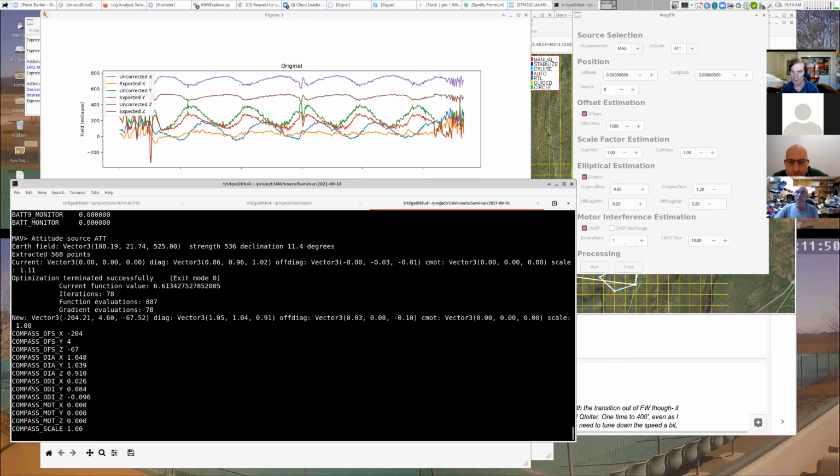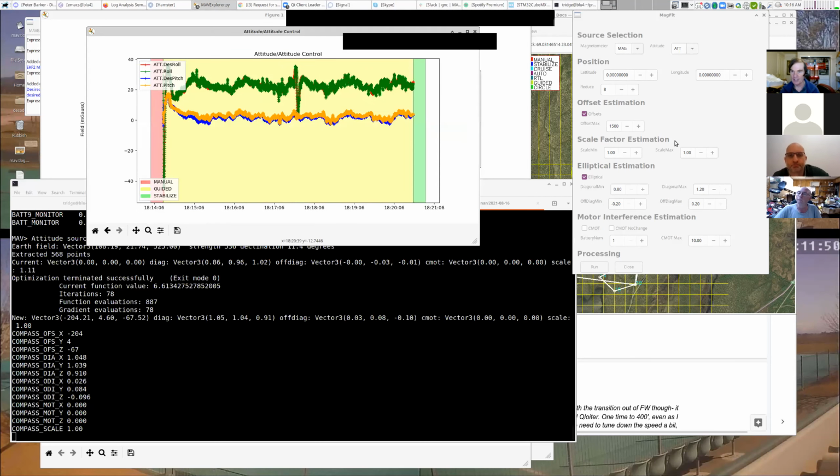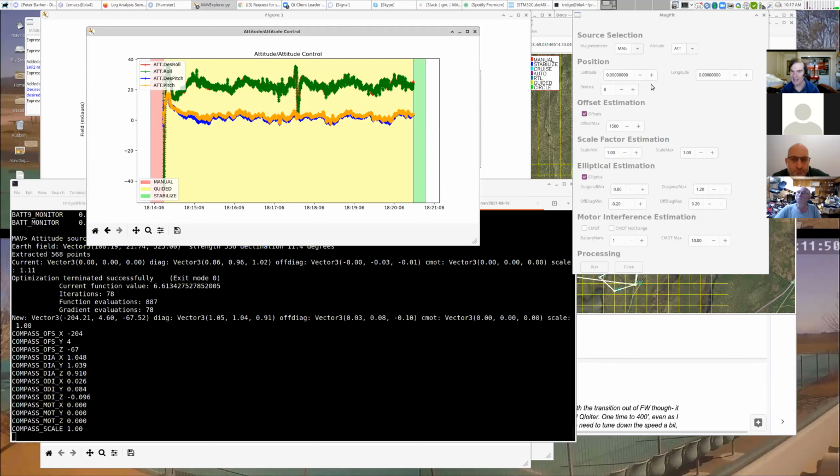You have to make sure that you include in the part of the flight that you're matching against a part where it does have significant changes in throttle. Otherwise it can't estimate it if it's always at the same throttle value. And I should note, the data that this fitter fits over is the place that you last zoomed to in the flight, right? So that's why I ended up with a bit less data here, because I zoomed only on this part of the flight.